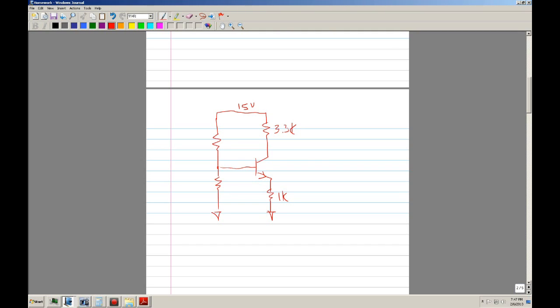Okay. Mira. So now we know we're establishing the current. We know that this is going to be 2 volts, and there's 0.7. You know Ohm's law, well, you've got to know diodes too. When anybody asks how many volts it takes to turn on a diode, the first thing you should say is 0.7.